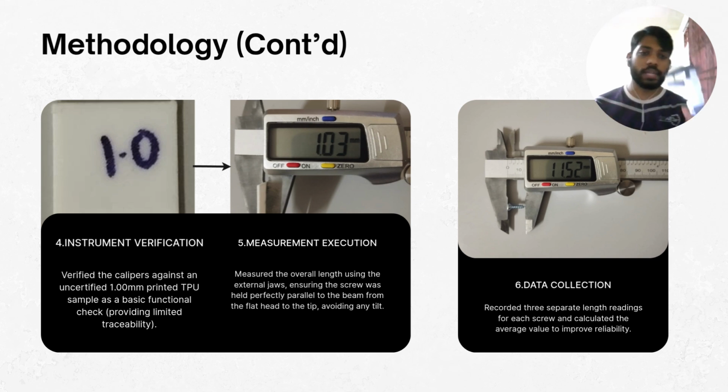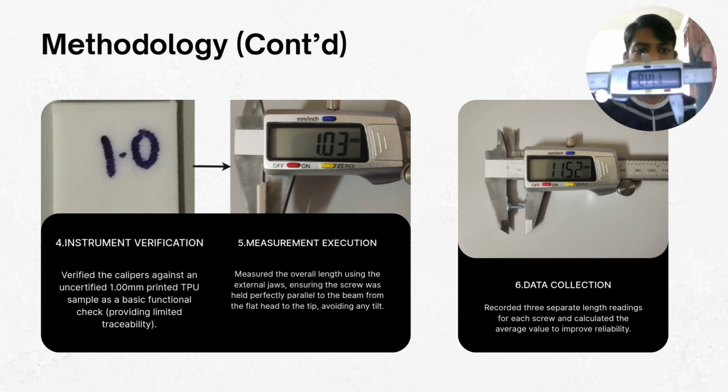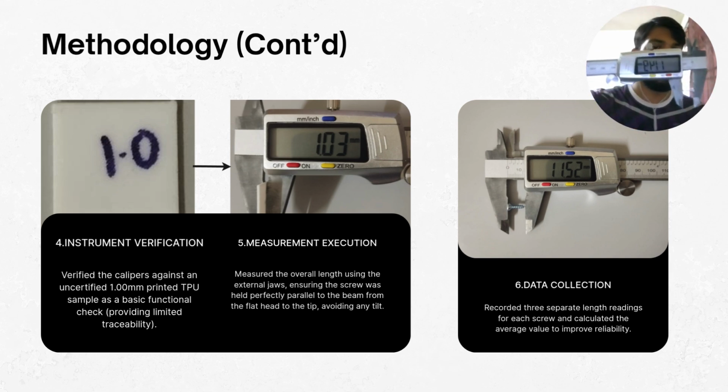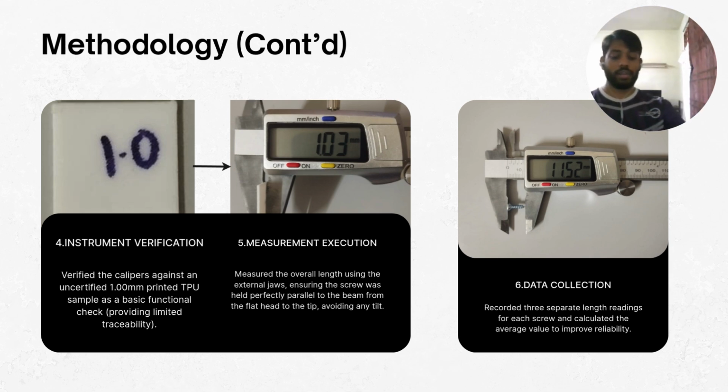Make sure it is not slanted, make sure it is as straight as possible to prevent any misreading from the screw itself. And as a precaution, we can use this top screw gauge and twist it to lock it, and we can have our proper reading. In our case, right now it's reading 11.49 mm of overall length. And later we're going to see the difference in length the screws are going to have, but 11.49 is considered the right amount of length for this machine screw especially.